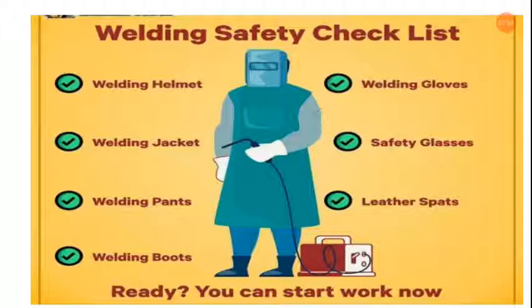Talking about the radiation, it is essential that eyes be protected from radiation exposure. Even a brief exposure to UV radiation can cause eye burn, known as welder's flash. While this condition is not always apparent until several hours after exposure, it causes extreme discomfort and can result in swelling, fluid secretion, and temporary blindness. Normally, welder's flash is temporary, but repeated or prolonged exposure can lead to permanent eye injury.